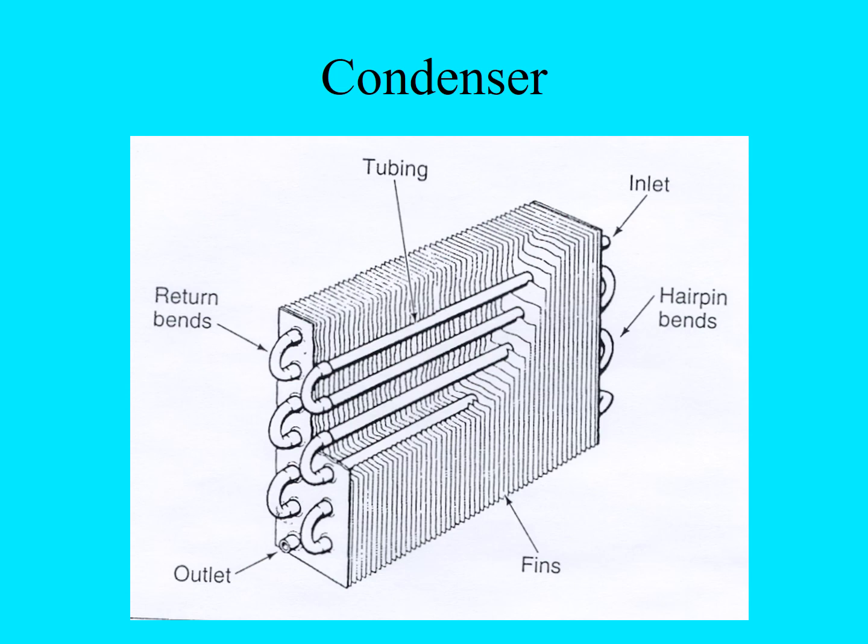Condensers, I've always said the condenser is usually the first thing that gets injured in a frontal crash in the refrigeration system. Now the cooling fins, if they get bent over, they can be combed out. If these get laid over so they're blocking air, they make a comb that's made out of plastic that has so many fins per inch, and there's like 5 or 6 of them on the comb, so you can match the cooling fins, and then you just rake through those and get them to stand back up straight again so the air can flow through there properly.